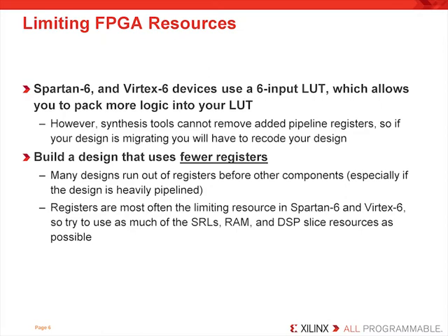So, right off the bat, keep in mind that you need to pipeline to a lesser degree, and you need to use as much of the dedicated hardware, that is the shift register LUTs, the block RAMs, the DSP slices, etc., as possible to shrink your device utilization of LUTs and registers. Getting these resources properly inferred can help you manage your design size.